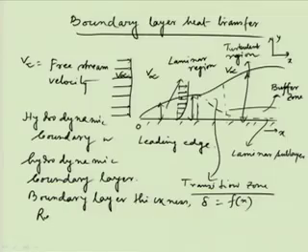The Reynolds number defined in these particular cases is Rex. It is usually called the local Reynolds number, and it is x rho Vx infinity by mu, where Vx infinity means V infinity along the x direction.